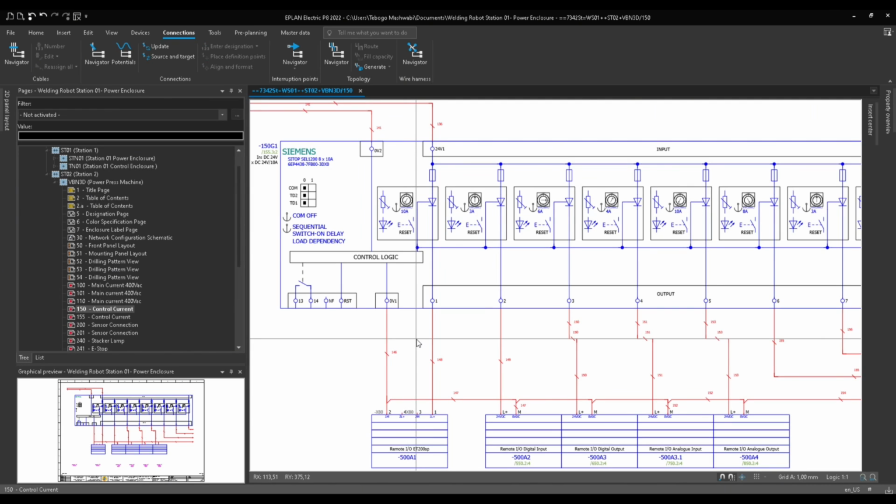My goal is to see which device the wire comes from and to which device the wire is going. I want to represent where the wire comes from and which device the wire is going to, so I'm going to show the source and the target. There are various ways, just like I mentioned. You can represent it according to the page, column, and also according to whether it's an L1, L2, L3. You can display it in various ways.